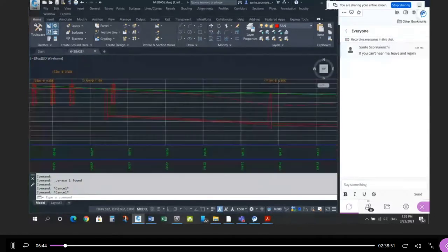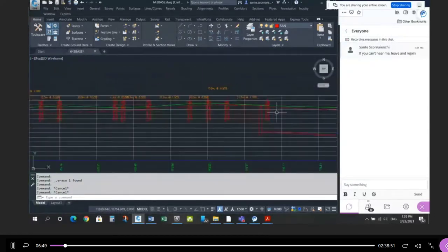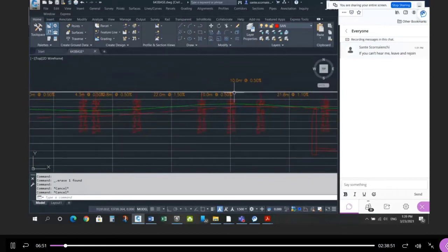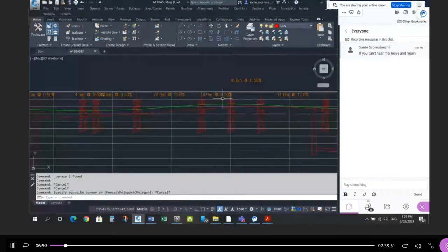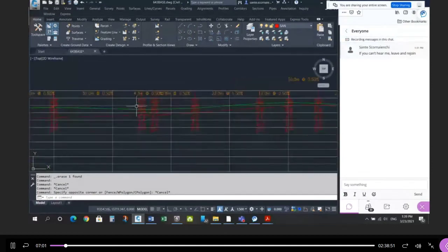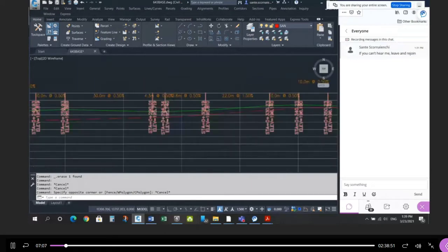So I can check that. And then the elbow at the other end was going to be 1.1%. And then I looked at the design, up at 0.5, down at 0.5%. There's your high point. Okay, I didn't look at the elevation necessarily, but I looked at the profile. Then down 1.5, down 0.5, down 1.5, down 0.5 for the intersection and beyond. So the low point is not at the intersection, but at the projection of the gutter line.